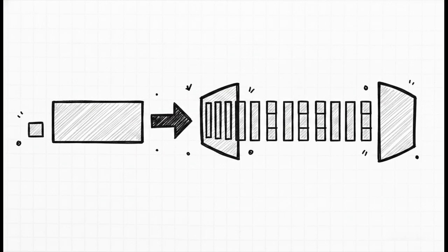So how do we apply all this in cutting-edge fabrication nodes? Well, let's say you have a massive output device compared to your reference, like a ratio of 1 to 15. That might mean 4 fingers for the reference and a massive 60 fingers for the output. You absolutely cannot just draw one tiny block and one huge block. You have to split that 60-finger output device into equal unit fingers that exactly match the width and length of your reference fingers. Once everything is broken down into these identical modular units, use a hybrid symmetric arrangement.